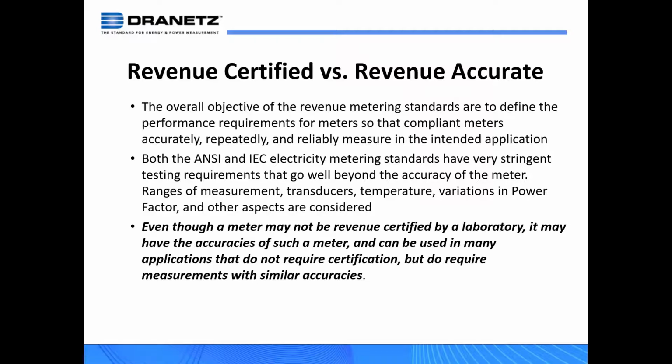So the takeaway here is even though a meter may not be revenue accurate or revenue certified, I should say, by a laboratory, it may have the accuracies of such a meter. Most of the Dranetz products fall into that. We have revenue accurate meters. They are just not certified for billing in the territories or regions. So they can be used in many applications that don't require certification, but do require measurements with similar accuracies.